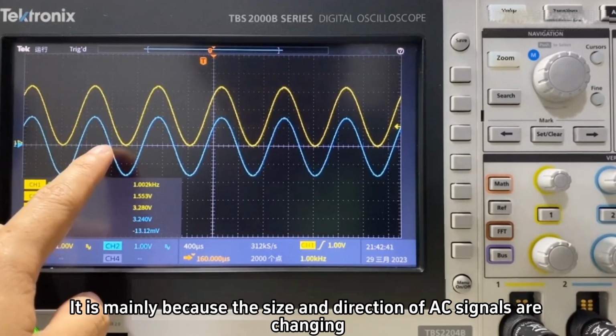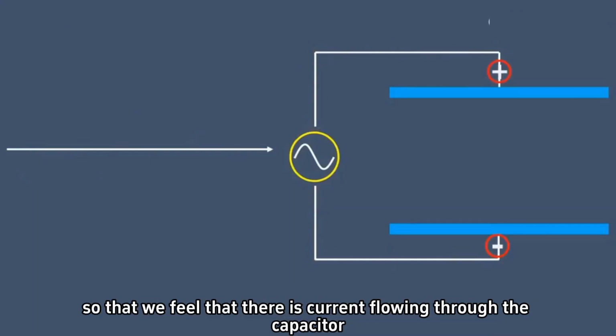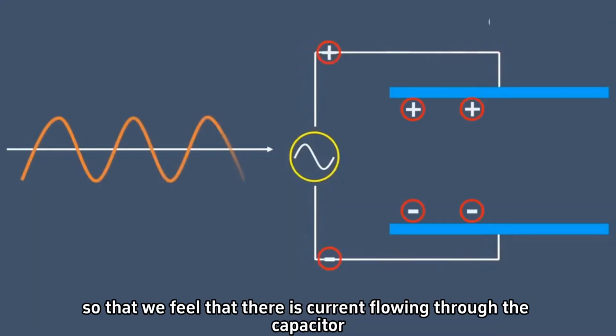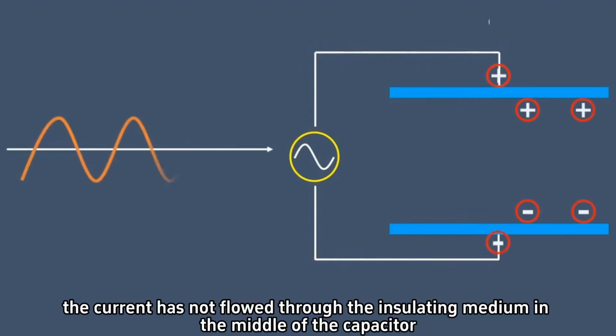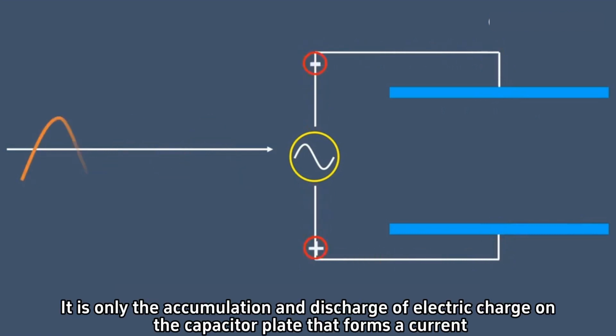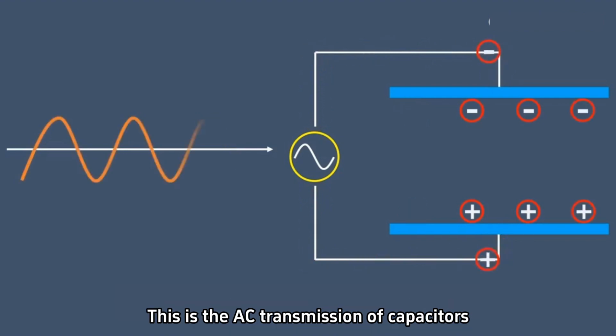It is mainly because the size and direction of AC signals are changing, which will cause the capacitor to continuously charge and discharge, so that we feel that there is current flowing through the capacitor. In fact, the current has not flowed through the insulating medium in the middle of the capacitor. It is only the accumulation and discharge of electric charge on the capacitor plate that forms a current. This is the AC transmission of capacitors.